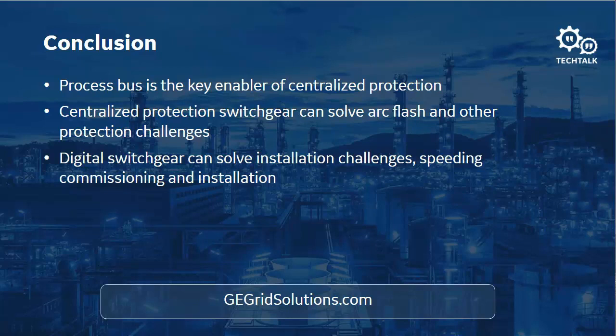Yes, you're correct. If you lost a part of the ring, for example if you lost one of the MU320s, you would still have the other way around the ring. That is the beauty of this sort of ring network, in that if you lose a section, you still have communications. You just no longer have the ring. The problem that I have with the HSR is that it does add some latency for each individual hop around that ring. It's not much latency, but it does add some.